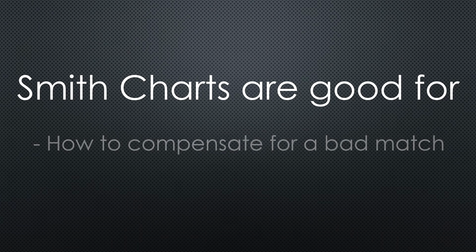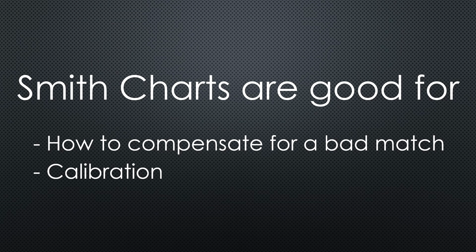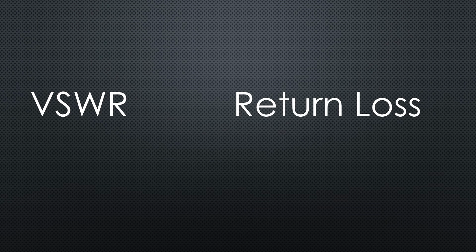When we want to know how we can compensate for a bad match, for example, and for calibration, as we will later see. By the way, if you talk VSWR to an RF engineer, he immediately knows you are an amateur radio operator. He would never use this word. He uses return loss in dB, which is the same, just different.